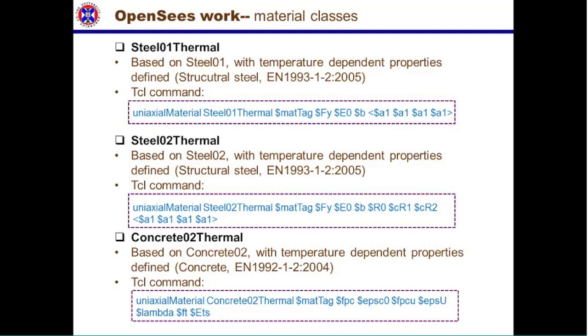And for Concrete02Thermal, it's quite similar to Concrete02 in the OpenSees framework, but we just added the thermal elongations, which account for the expansion of the fibers, and the reduction factor of the stiffness, which applies to the tangent modulus.